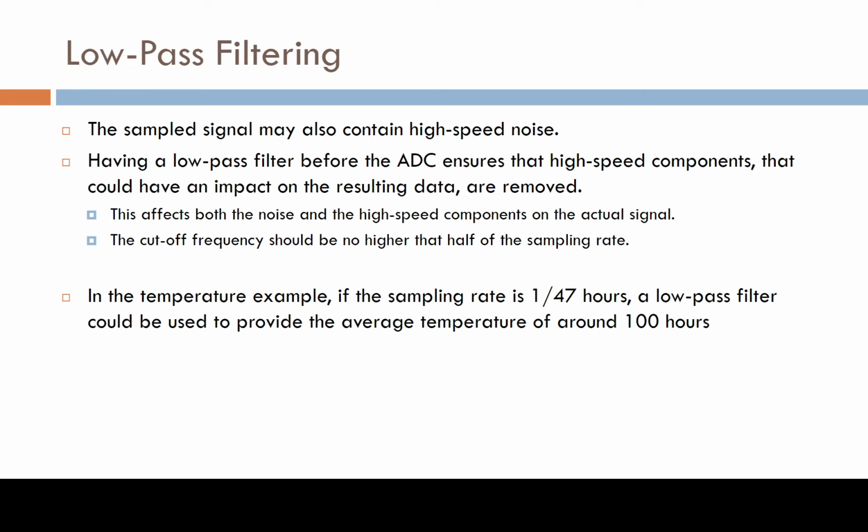So basically, quite often in digital signals, you need to do some low pass filtering. If you have a low pass filter before A to D conversion, then you can prevent aliasing effect on the data. But you can also reduce the amount of noise before sampling.